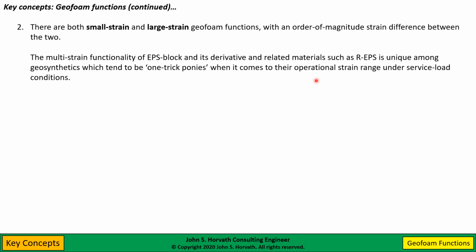I mean, we all know, for example, if we are designing, say, a mechanically stabilized earth wall that is using geogrid, that there's kind of a magic strain level that we've settled on to design for. So there's a very limited strain range that we look for in design of that geogrid. Certainly, we don't typically have geogrid installations where, in one case the strain is 2%, in another case it's 40%, something like that. What we do with geofoam for pressure reduction.